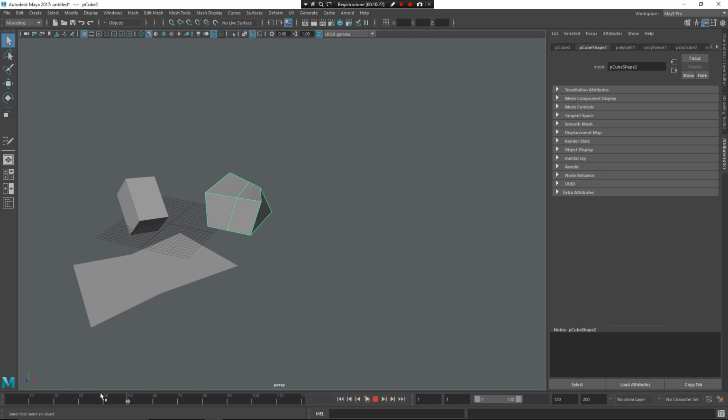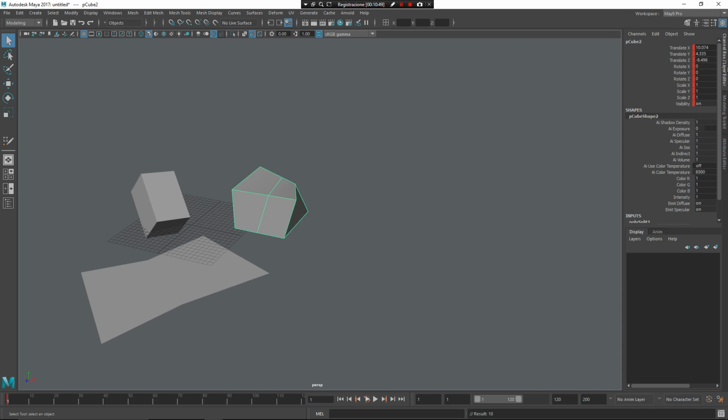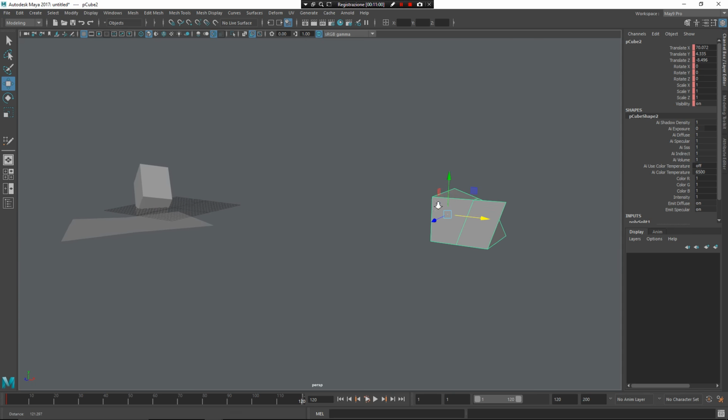This area is the timeline. This is the time. This is the past, the future, and the vertical line is the present. So I can drag my time back and forth by using the left mouse button and dragging inside of this area. Then go to frame 1. Press S to save the key. Go back to my channel editor. Alright, now I can press W and then go to the end of the time and push my object in its forward direction.